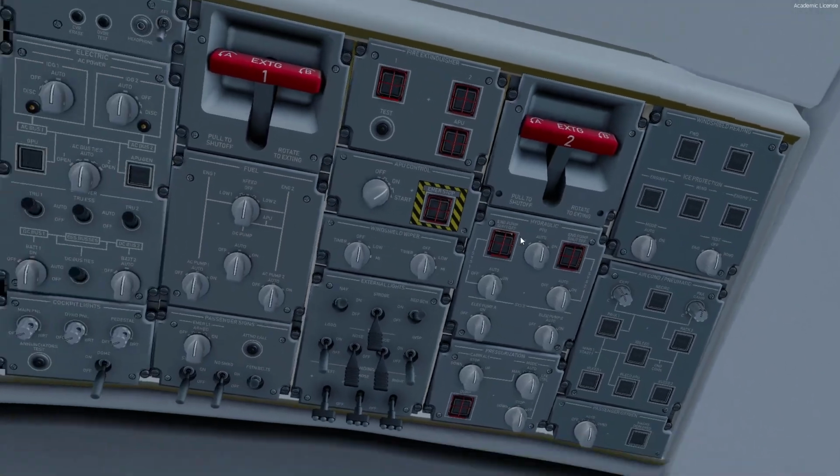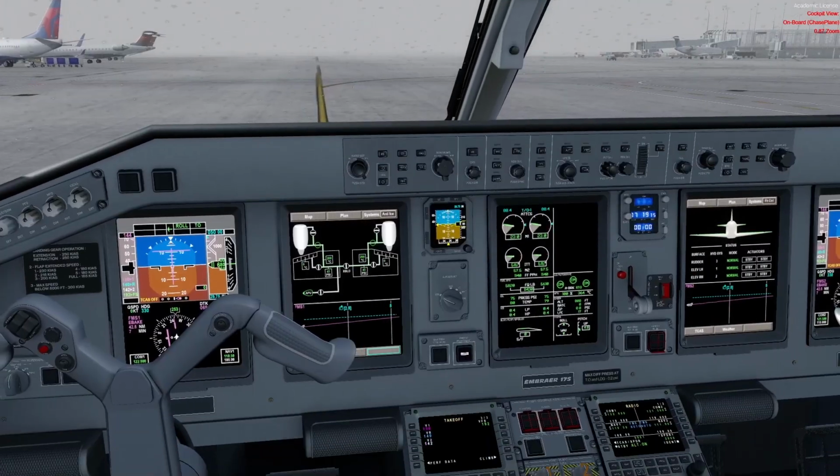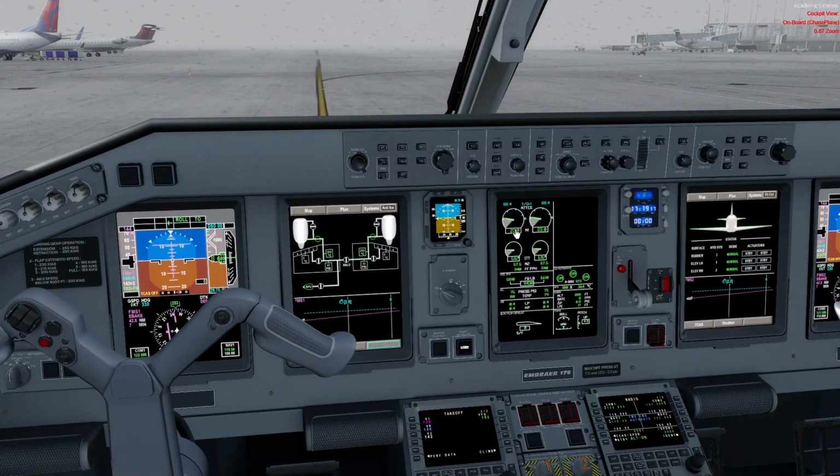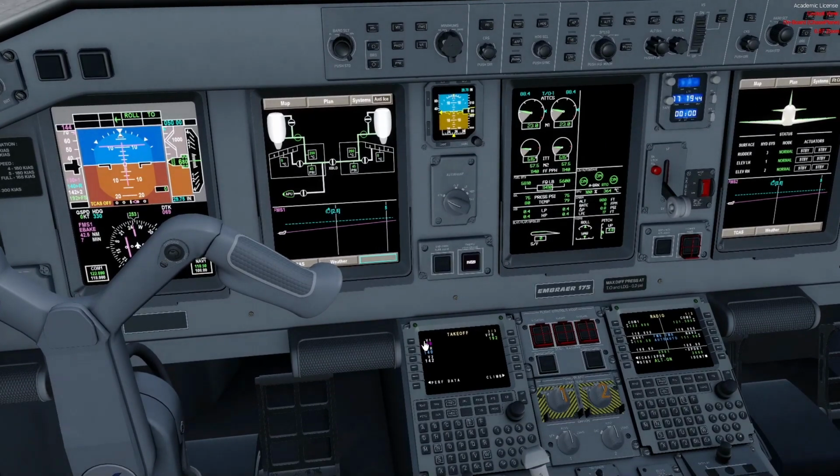And then as it comes down to setting up the performance, we would usually set the performance at the gate. Not always, or sometimes there's a change. Sometimes there's a change in the departure runway, or sometimes the temperature dropped, say from 11 degrees before we pushed to 5 degrees by the time we had a delay and there's a cold front coming, and now it's cold. So I took the liberty to do the rest of the performance, as in the zero fuel weight and the takeoff performance, etc.